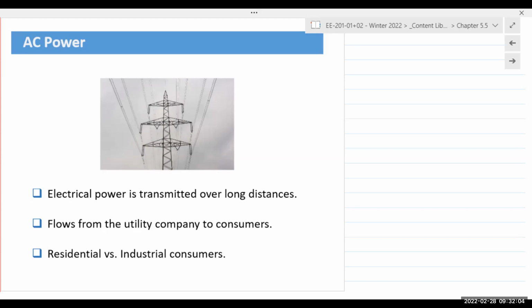A capacitor works the exact same way, except that a capacitor is a dual and opposite of the inductor, meaning when the inductor receives the energy, the capacitor behaves the opposite. The capacitor sends the energy out. So in the same half cycle, if an inductor is sending the energy out, the capacitor is receiving the energy. And this is very important because of a technique that we will use later on in this chapter. That technique is known as power factor correction. We'll talk about it in just a little bit. But why does this energy exchange matter?